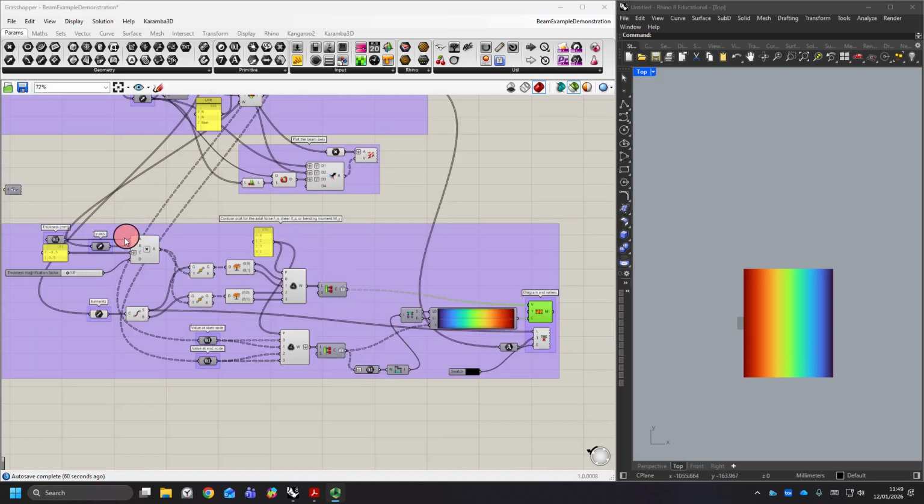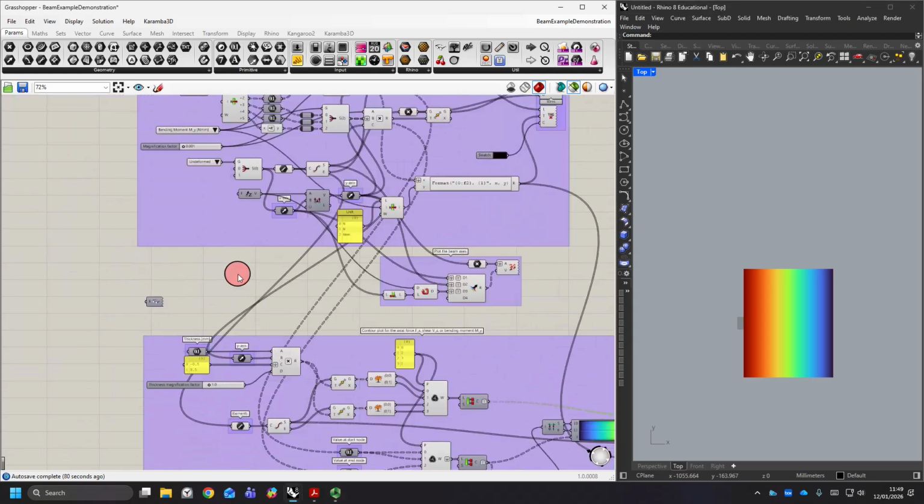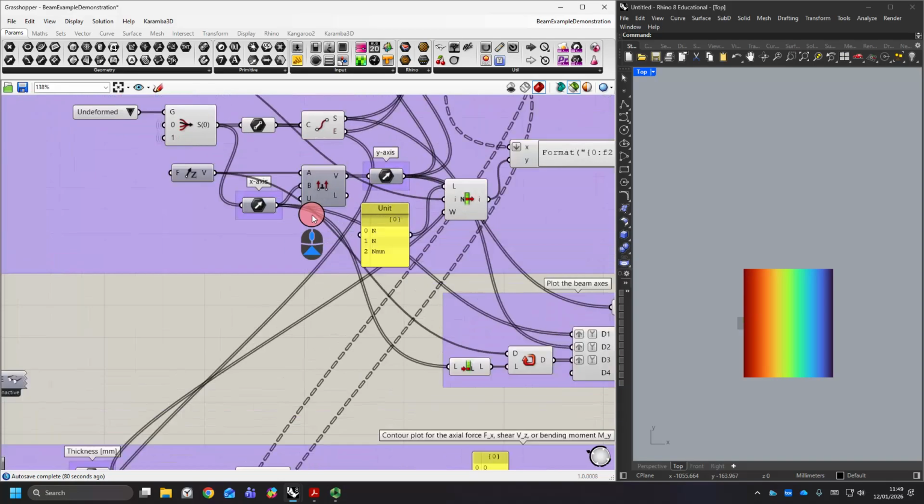Okay, so what's gone on here, if I just look at the vector, we can see that the value for the y direction in that is quite high, so 125. And it was just because of the way that we generated it back here in the cross product component. And what I hadn't turned on here was the unitize, so basically to make the vector length here 1.